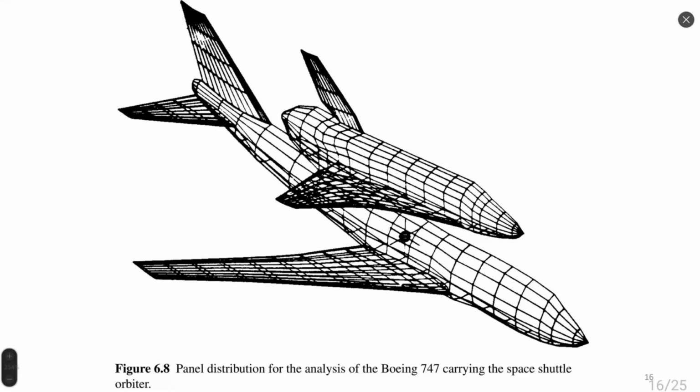I would like to remind you that this method you see is not CFD, it is a solution of the potential equation, right, of just one equation. And it's many times simpler from a computational point of view, from number of calculations and required time for simulation, and at the time of design of such vehicles, it was the only method to evaluate aerodynamic properties numerically.